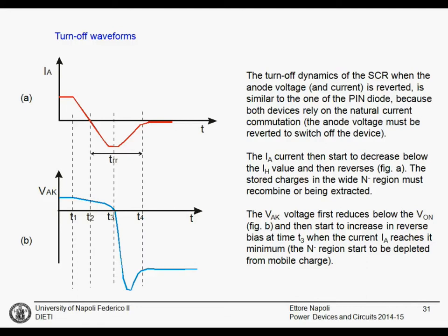This is actually reducing the gain of the base. This is like making a smaller cathode or diverting a portion of the gate current to the short, but only a portion of that. The remaining portion of the current will switch on the device. It will be more difficult to switch on the device. You will probably need more current, and then which is the advantage?